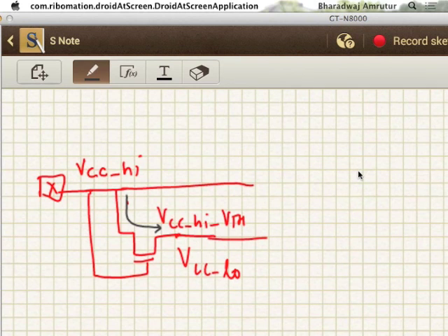So if you want to use this NMOS, periodically you have to discharge it. You might have to have a setup where there is some other circuitry, like a reset, and then it resets it. So then it becomes a messy thing. What happens is, if you look at this voltage here, it slowly goes up, then you reset, then again it goes up, then reset, and so on. So it doesn't work well.